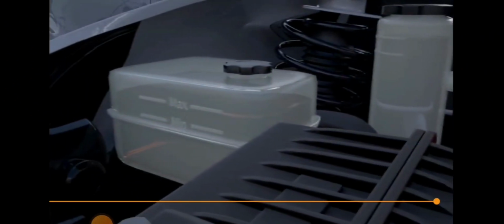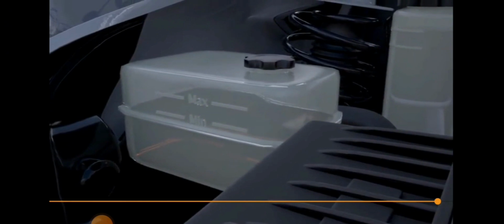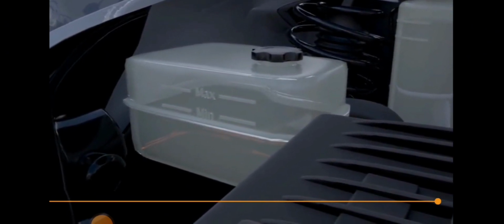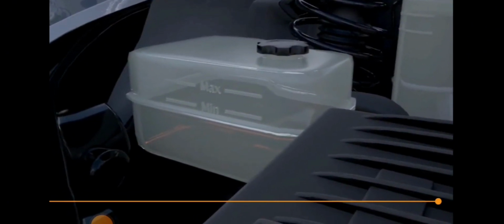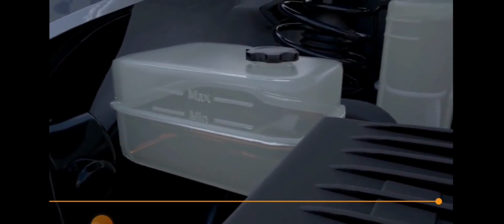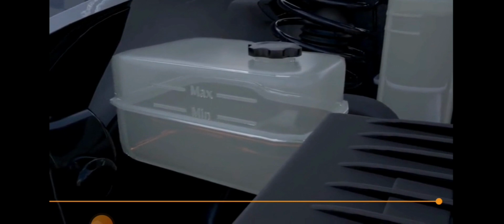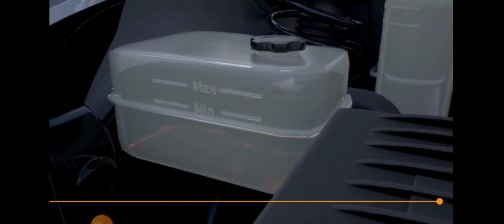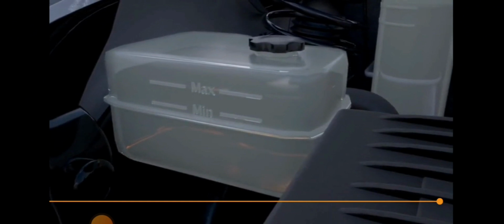Brake fluid. Brake fluid level must be checked weekly, where the decrease in brake fluid is normal and must not be increased except in case of decrease below the minimum level, where the decrease of fluid level in brake fluid reservoir to the minimum level means that front brake pads need replacement, and after its replacement, the fluid returns to its normal level and there is no need to increase the fluid.